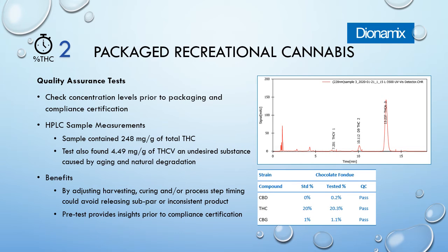I will start by first explaining the graph and the table data. The graph is arranged by showing the light detector absorption signal level over time as the separated compound exits the column. The light detector measures the absorption. The higher the density, the higher the level of absorption. What you see in the trace are the individual compound peaks, absorption levels or relative concentration as they exit the column.